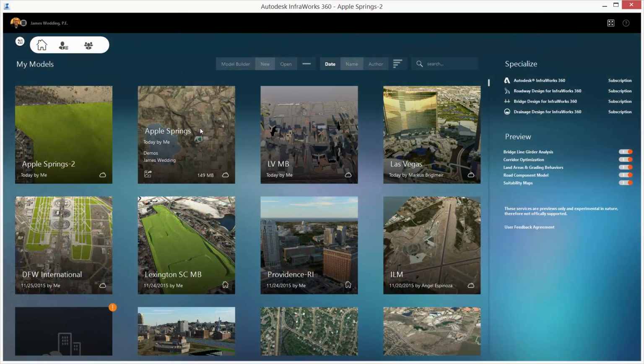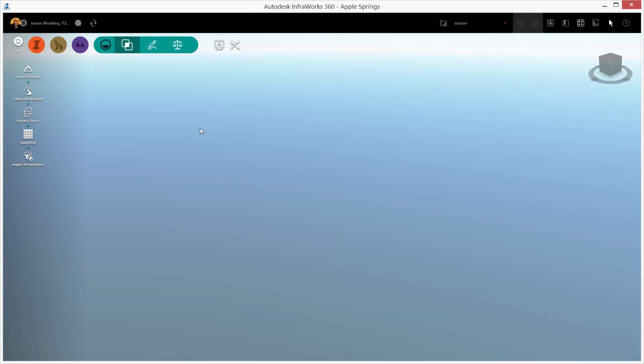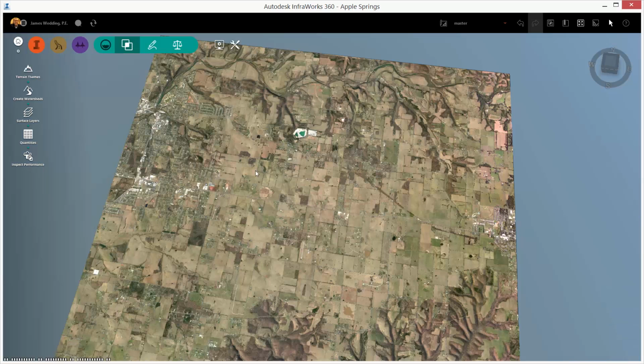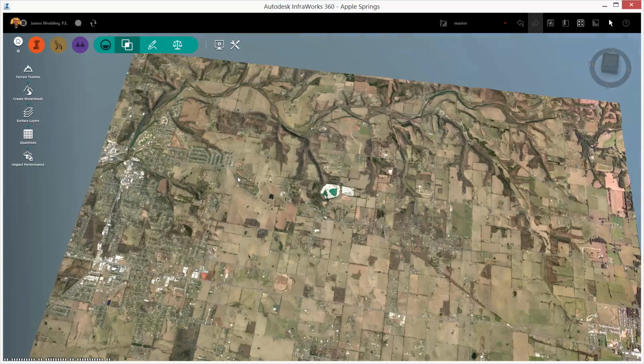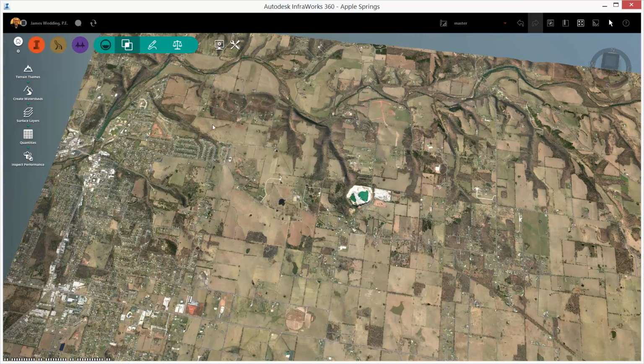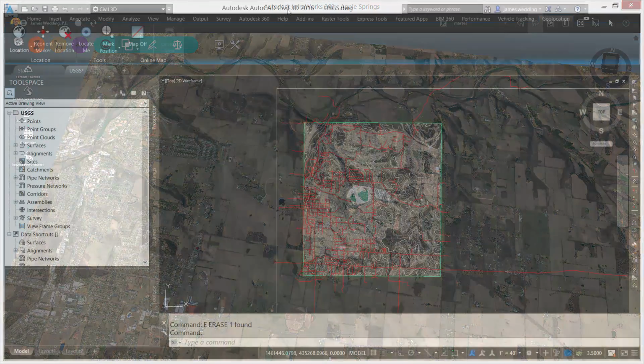When John created this model originally, he selected a pretty tight area around our site. In my new Model Builder run, I select nearly the full 200 square kilometers and generate an entirely new model. With this model, I can run the same watershed analysis, and I find that the contributing area is indeed much larger than I first thought, and that I was smart to double check.